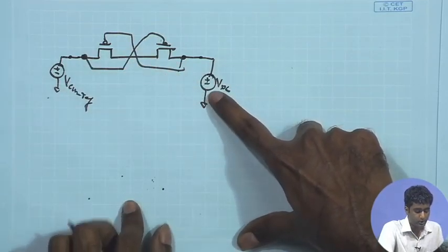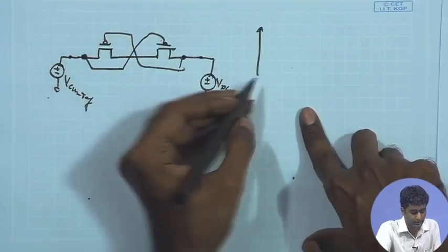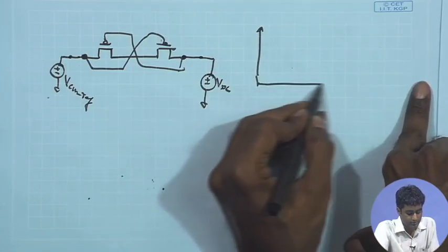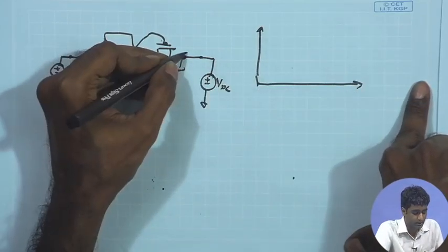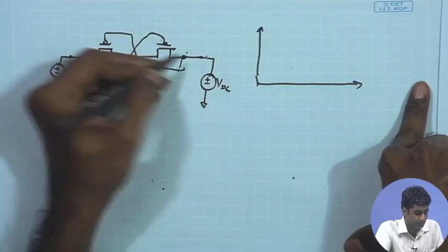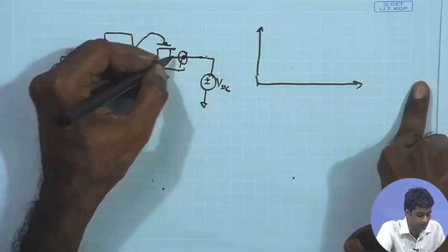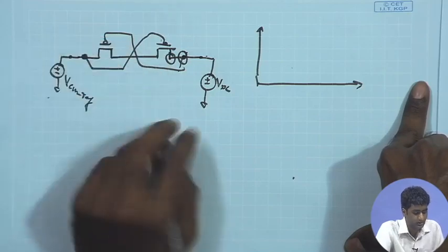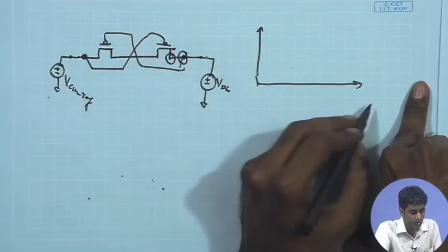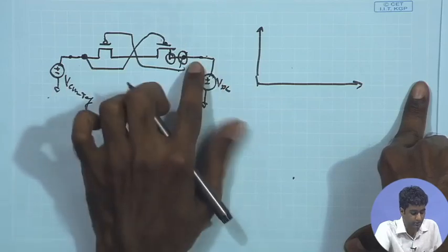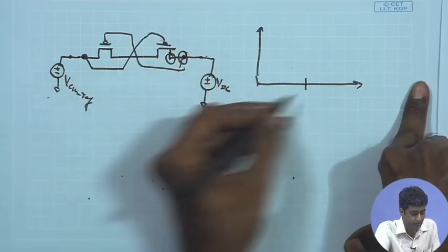look at the overall variation of the current across these resistors. So, you can put a marker over here, basically a marker at the source of this PMOS, and then you can plot the overall I as a function of VDC. So, VDC needs to be swept across VCM ref.